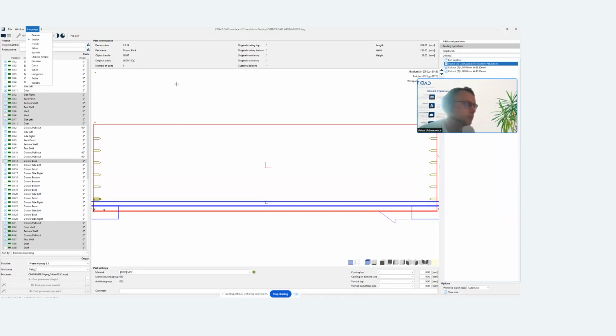And for the pocketing, sometimes you decide to use the clear area to be routed in, but your groove is so narrow, and you are confident that the final contour will do the work and the roughing won't be so necessary. Then you can deselect the clear area. Then the system will ignore the clear area from the pocketing manufacturing group, and only trigger the final contour.